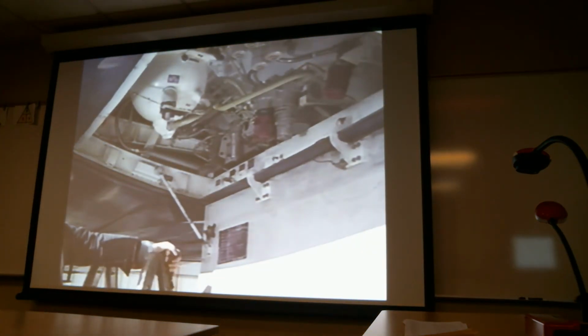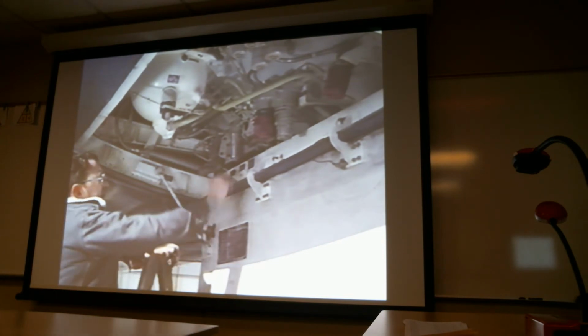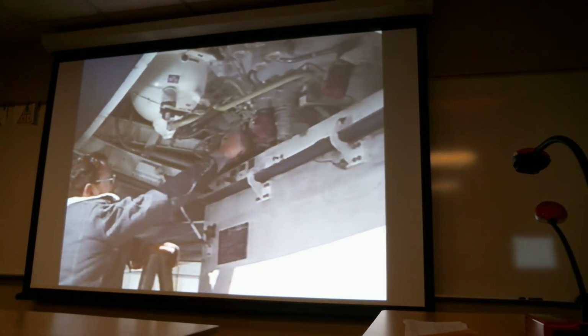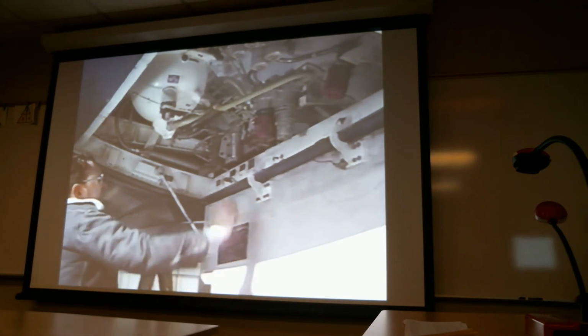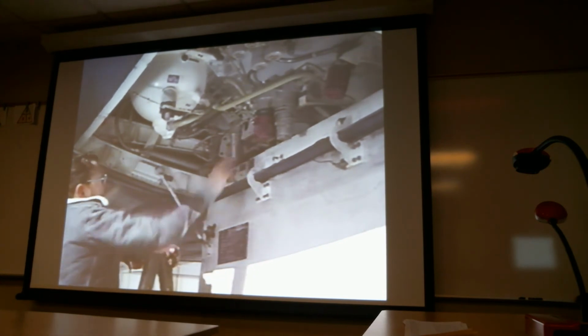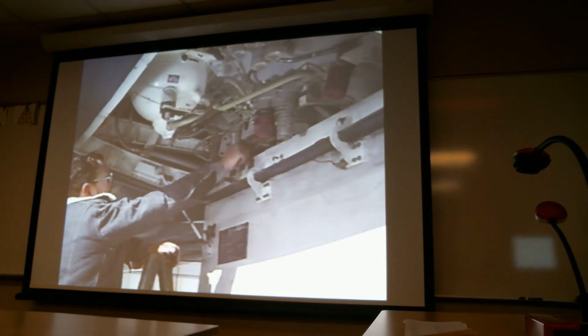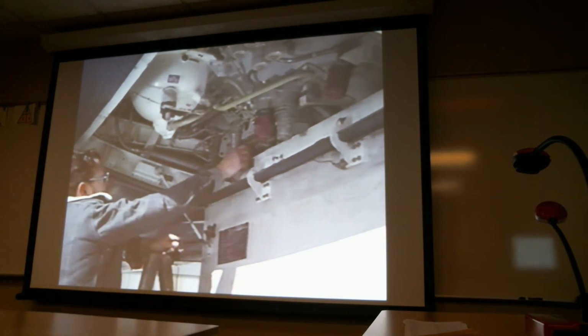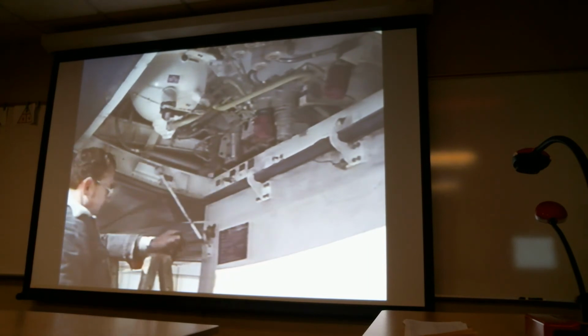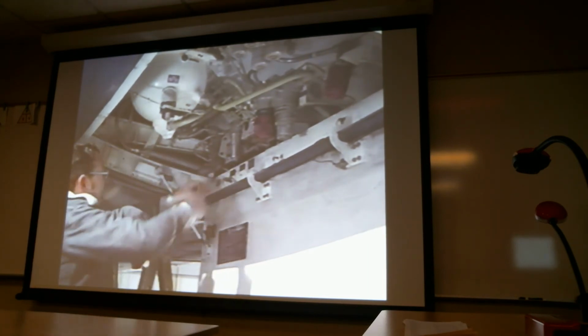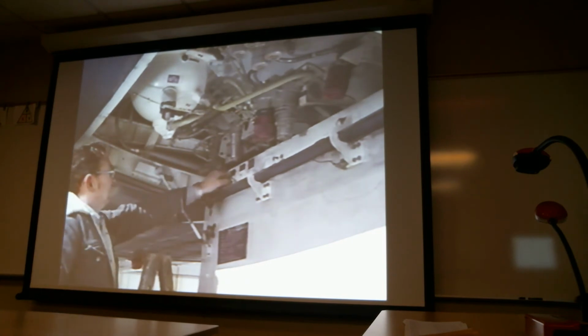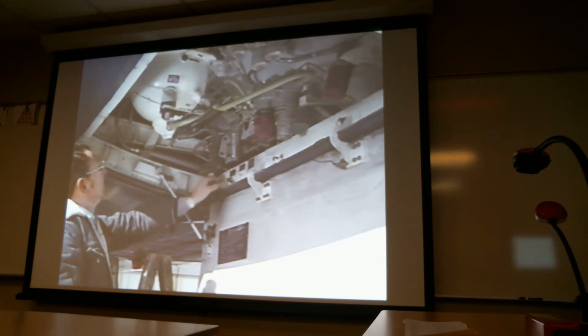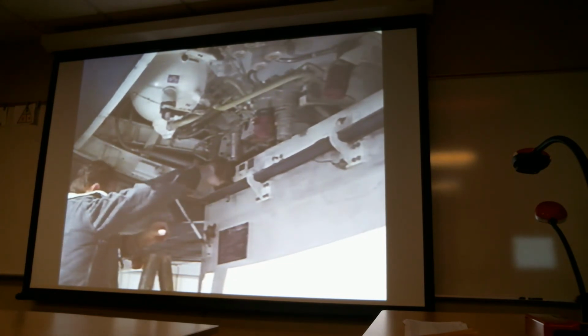To service the hydraulic system through the pressure fill port, proceed with the fluid level check as before. Set the selector valve to the reservoir to be filled. Remove the dust cap from the pressure fill port and wipe the fitting with a clean, dry cloth.